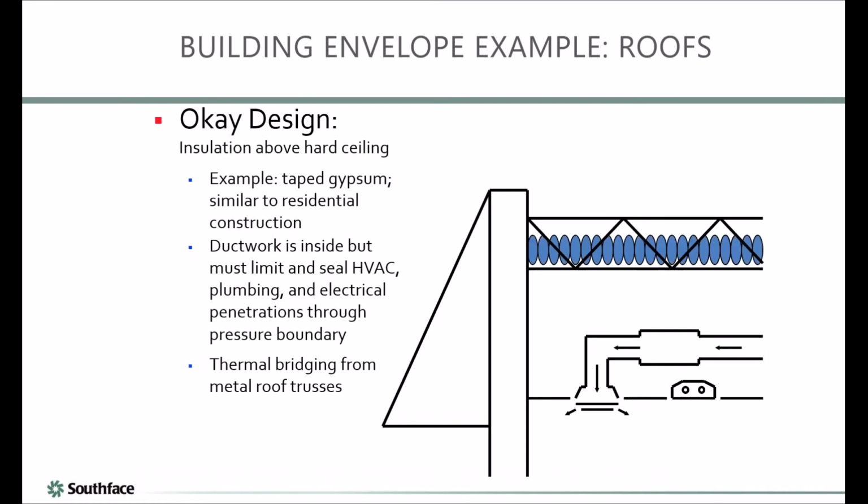So a way that is allowed is to put a hard air barrier and then insulation on top of that, kind of like an attic assembly. It's got its set of issues too. Very often this is hidden and therefore gets violated. Somebody will poke a hole through that ceiling as well as that wall because it's all hidden. I would say too, Laura, this reminds me that I like the cloud approach.